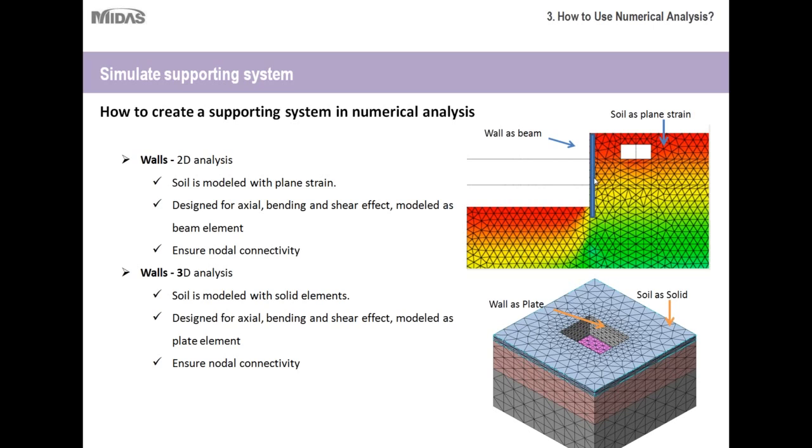your proper strains, etc. Now, when you're doing a 3D analysis, the soil is modeled with solid elements, also known as 3D elements. As you can see, all of the surrounding soil here is modeled with these 3D elements. And then the wall itself is designed for axial bending and shear effect, and this time it's modeled as a plate element, not as a beam element.